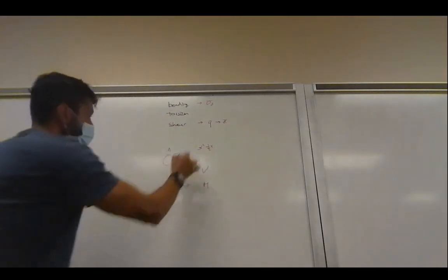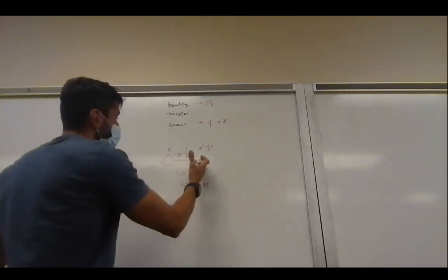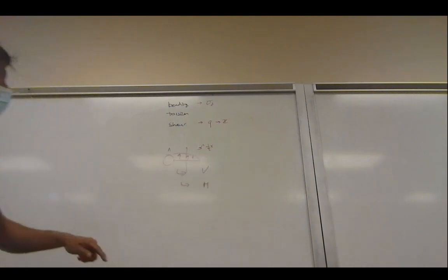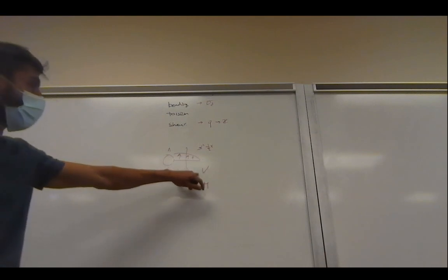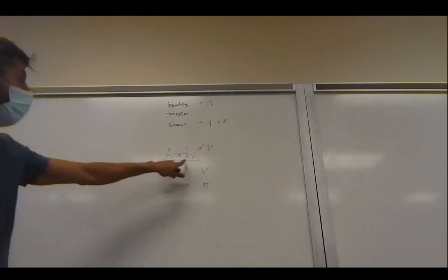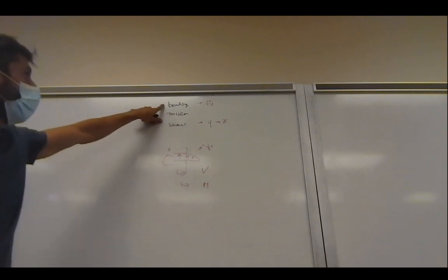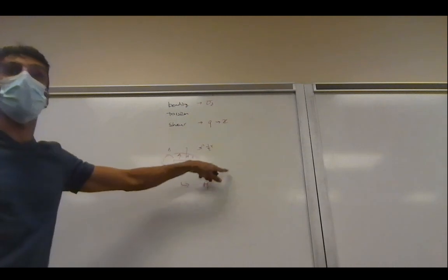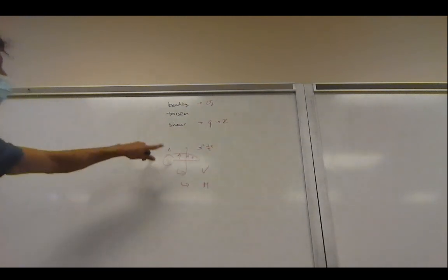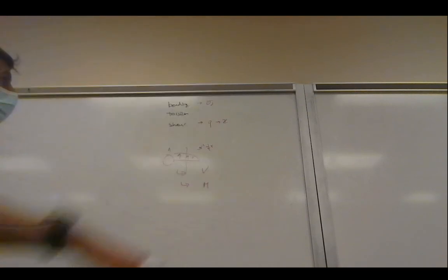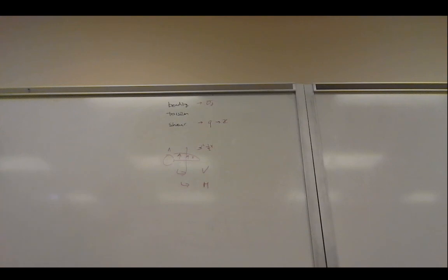So now, say for example, you want to look at the middle of the beam, you can calculate based on external loading what the internal shear force diagram and moment diagram look like, and then you can use those moments and shear forces at those locations to fill in the bending equation and the shear flow equation to get the stresses, and then you can say something about failure. So again, even if you have a complex loading structure on your wing, you can always decouple it into the building blocks that we talked about in this lecture series.